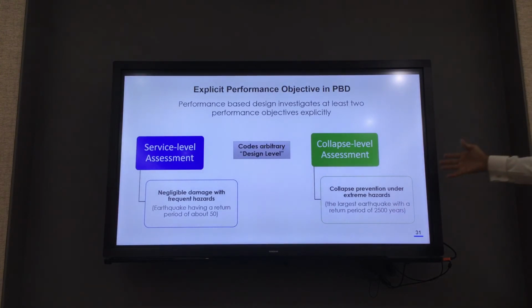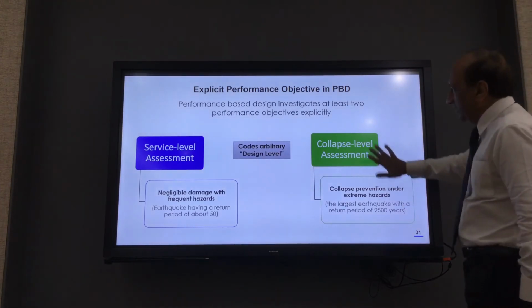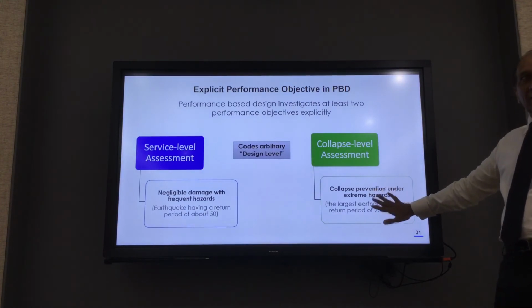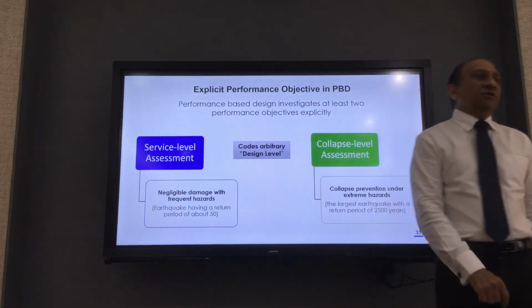Then there is the life cycle loading when the structure experiences something extremely extreme, something that has a very low probability of coming, 2% or less, right, in the lifetime of the structure. Extremely low probability, but we still don't want the structure to fall down for that. So we check collapse prevention for that level, and serviceability for the other level.